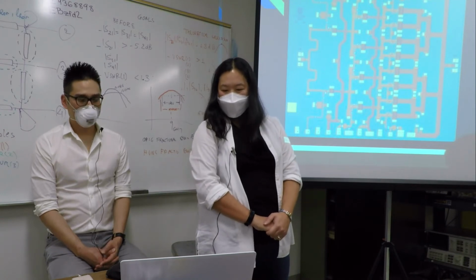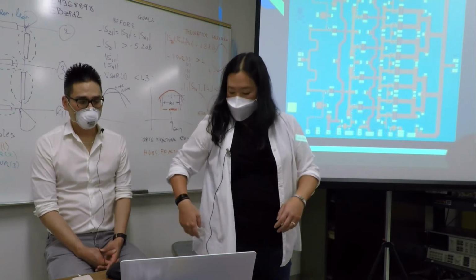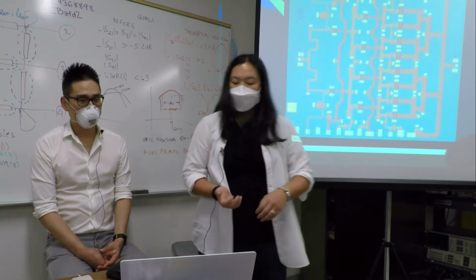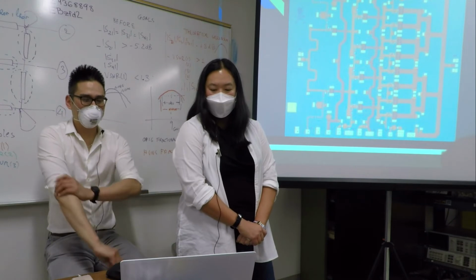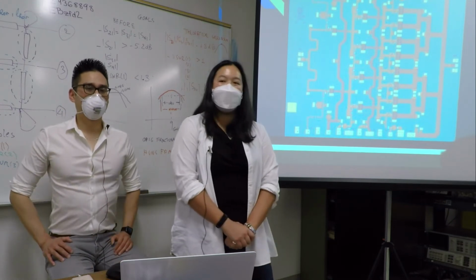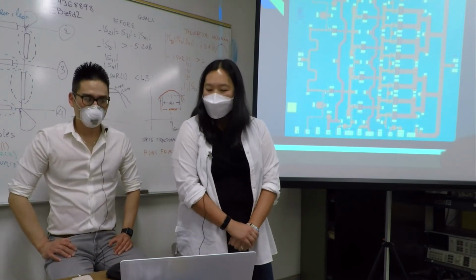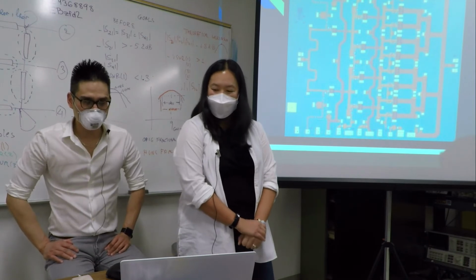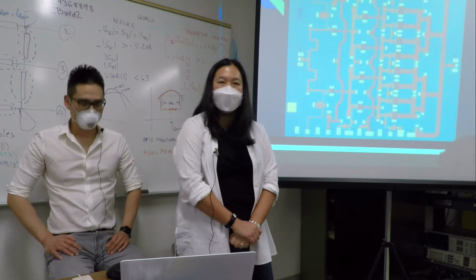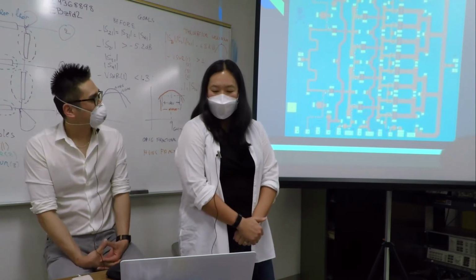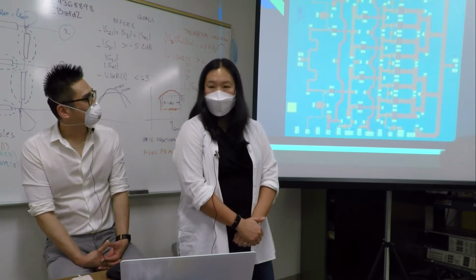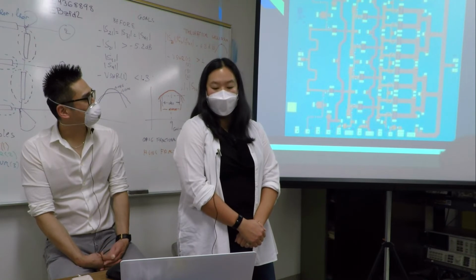What are the kind of specs that you've seen defined for a PA? What are the important specs? Well, obviously for a PA, the most important is power. And then you have PAE, power added efficiency. It's the ratio of the output power to the DC power. And what frequencies does this operate at, would you say?